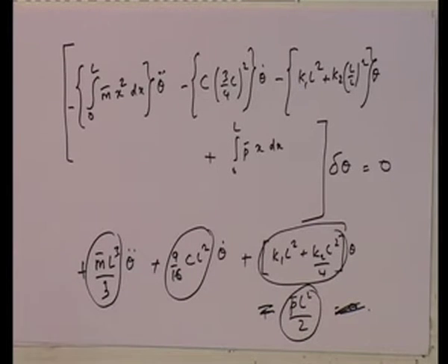Note that I have got exactly the same equation that I got by the equation of equilibrium, where I took moments about the left point to be equal to 0, because that's obviously at a hinge it has to be equal to 0. I have used the principle of virtual displacement, where all I have done is I have given a virtual displacement that satisfies all geometric boundary conditions, and I have just taken the virtual work done and put it equal to 0. Okay. And so, I get exactly the same equation.